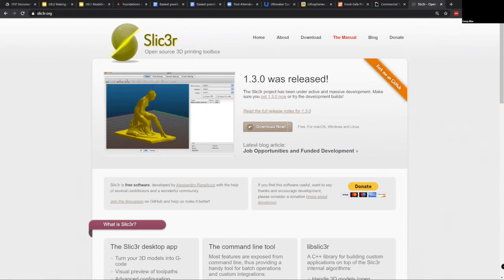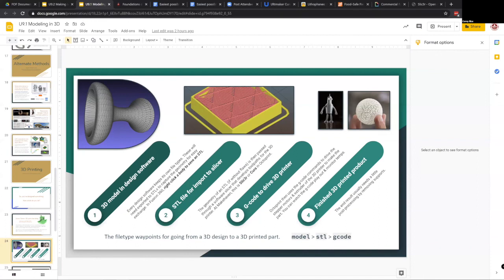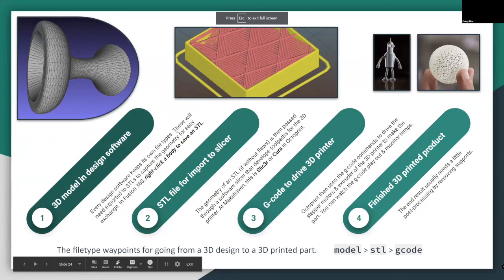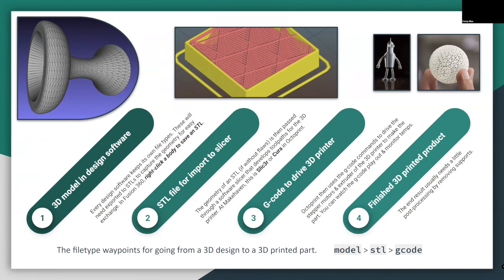If you wanted to install this locally, some people really like to walk into MakeHaven with an STL to be ready to print. Other people want to walk in with their own G code to be ready to print. Because I can never remember the size of the printers at MakeHaven, I usually show up with an STL and then slice it there with the printer right next to me. But that might not be true for all of you. You might decide that you want to have a little bit more control or be in charge of that in the right moment. So if you wanted to install Slicer or Cura, you totally can on your local machine. It's worth doing just to see how that goes. If you're going to design and then slice right there, you can bring your G code or just play around with it to get comfortable with either of those slicers to make G code for a printer.